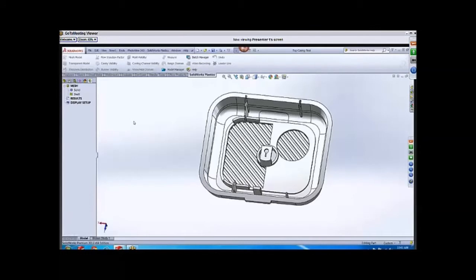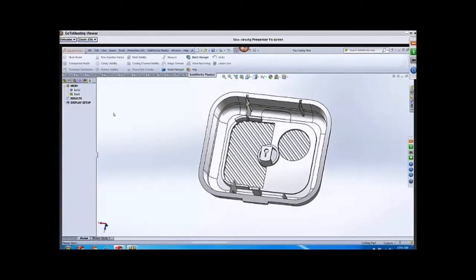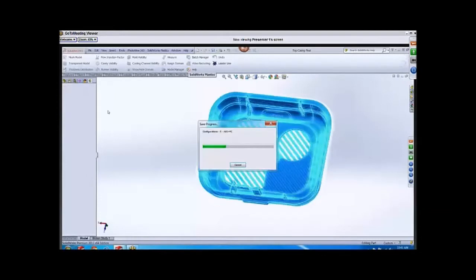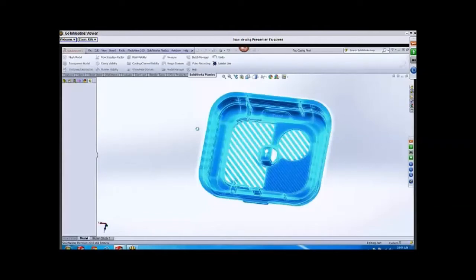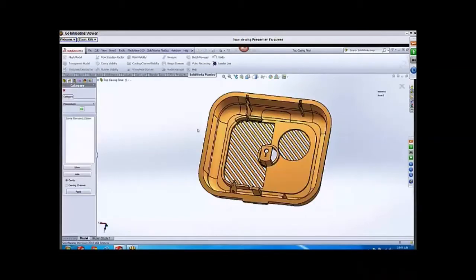Okay. So the first step is to create what's called a mesh. And the mesh is really just a way that our simulation products break down this complicated geometry into something that's small and easily workable. Plastics breaks down the model into triangles, and it's easier to figure out the flow of plastic through a triangle than almost any other shape. And so that's why it breaks it down into triangles. It's a little bit technical, so I'll just skip over it.